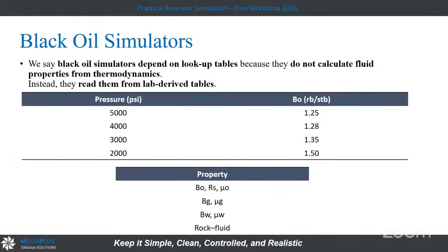So again, for the black oil simulators, it's the normal schedules that we got from the lab, from the experiments that I showed you, the DLE and the CCE. In the CCE, we agreed that the cell is closed, we will not produce. So we have constant mass, but we will know the saturation pressure. And for the differential liberation expansion, the DLE